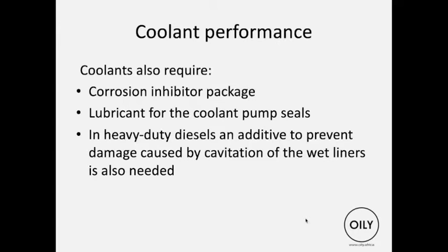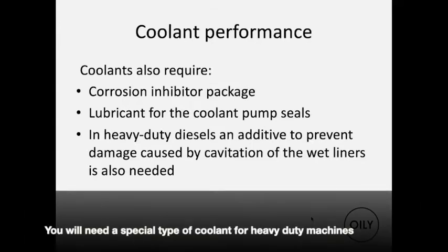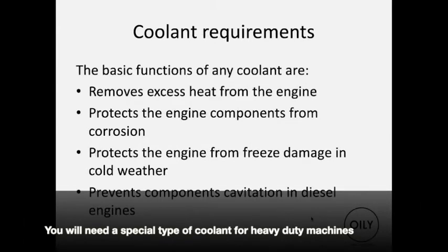As it expands, the water that's up against it suddenly gets displaced, and you can form bubbles in the water, and then the bubble implodes and starts pitting the liner from the outside. So you need an additive to prevent that. So you need a special type of coolant essentially for heavy duty.